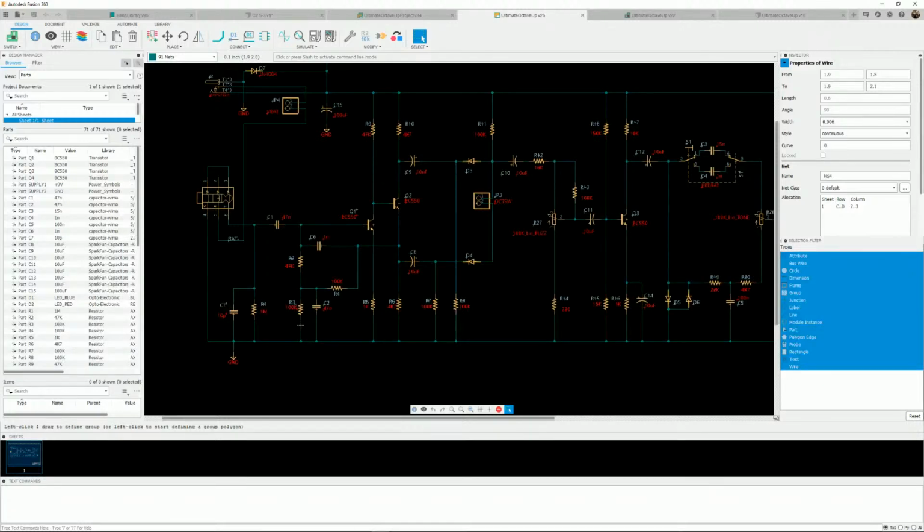So this second stage is also differential. As this transistor turns on, the collector voltage drops and the emitter voltage rises. So this is a phase splitter as well. We've got some gain in a phase splitter, and then we're half-wave rectifying the two out of phase signals. And when we mix those together, you get something close to a triangle shaped waveform from the guitar, something close to a triangle shape that's an octave above the note you're playing, but there's still a lot of harmonic content.